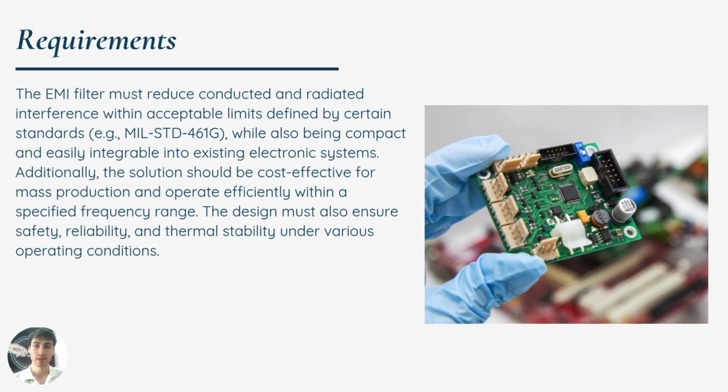The EMI filter must limit conducted and radiated interference under some standard limits, such as MIL-STD. And it should be compact, cost-effective, and work in the target frequency range. The design must also be safe, reliable, and thermally stable.